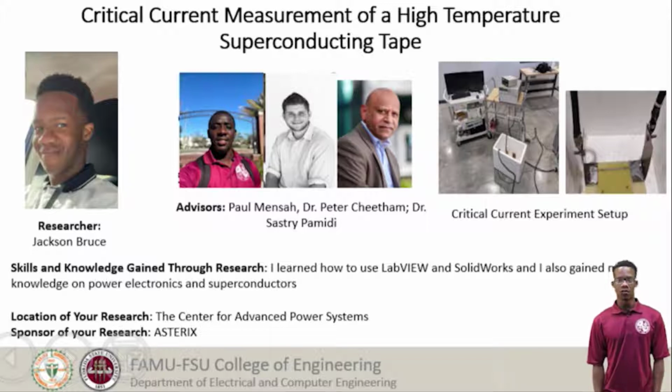The tools I used were a shunt resistor, voltage taps, ramp generator, current power supply, high-temperature superconducting tape, and a National Instruments data acquisition card. The National Instruments data acquisition measures both the current from the current power supply and the voltage across the high-temperature superconducting tape.